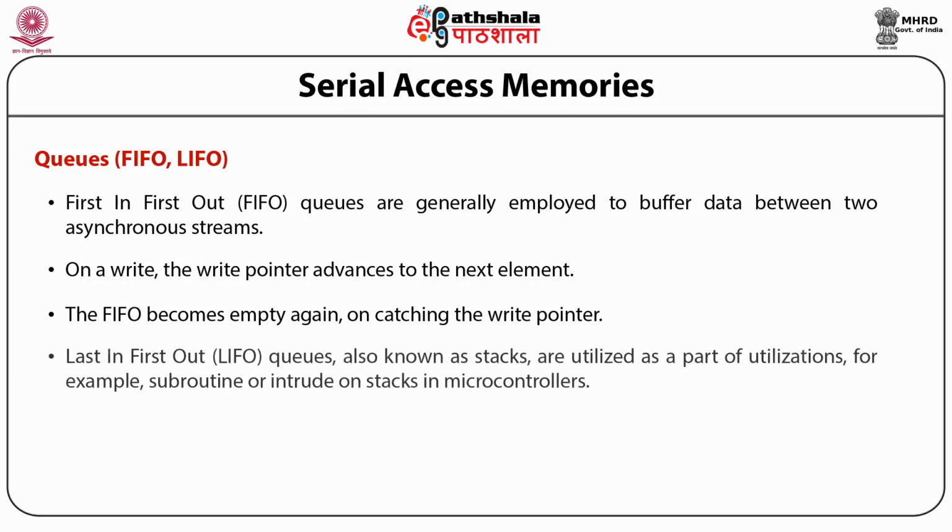Next is last in, first out, LIFO queues, which are known as stacks. They are utilized in applications, for example, subroutine or interrupt stacks in microcontrollers. LIFO uses a single pointer for both read and write.